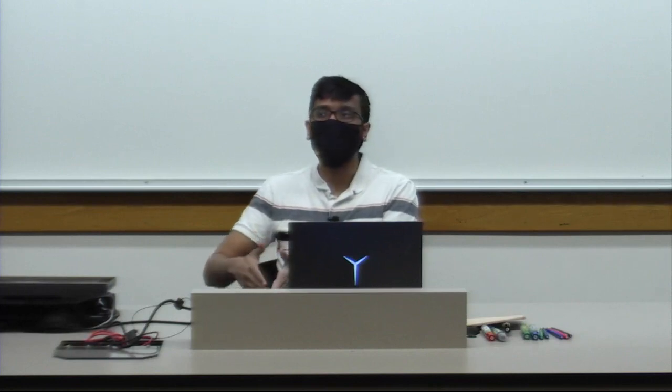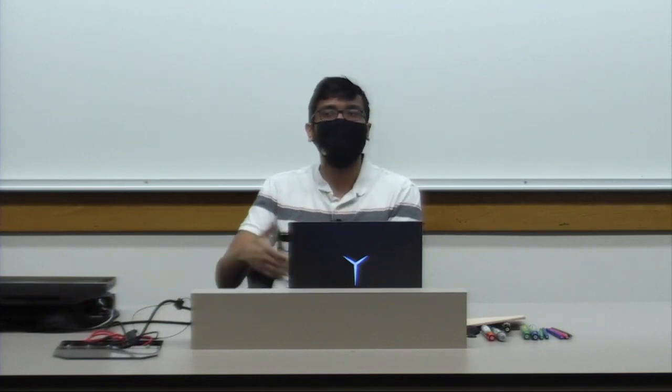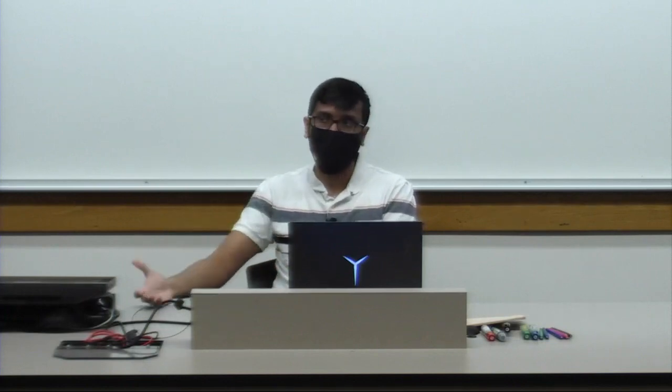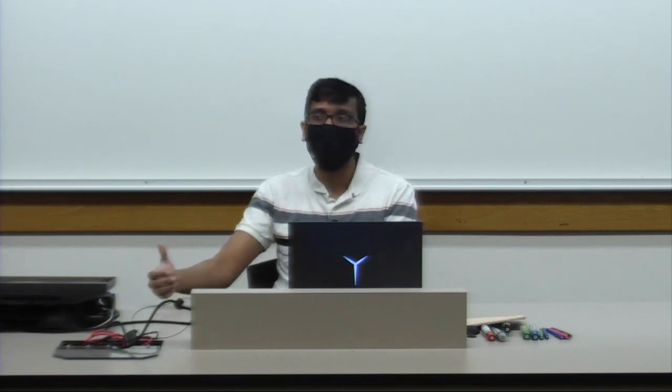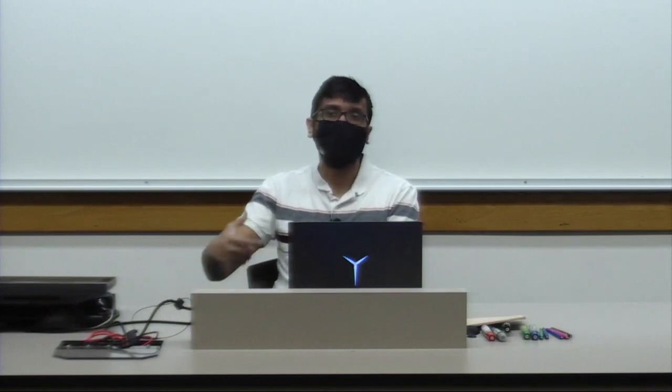A negative slack would mean that your critical path is greater than your clock period, which essentially means your design is failing, right? If you have a positive slack, you're within your clock. If you have a negative slack, your design is failing. In a lot of problems, we have asked you to report the critical path time. You would see the slack of the design, you know the clock period of the design, and from that you can calculate the critical path time. Does that make sense?